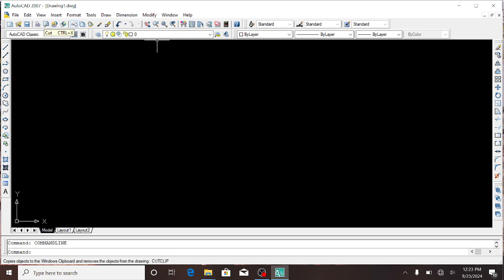In the standard toolbar, when you want to launch a new AutoCAD drawing, you can launch this from here, New. Then when you want to open your file which you have already saved, you use this. When you want to save, you click this button and it will be saved. This one is Plot. In AutoCAD, plot means just print. If you want to print your drawing or whatever you have done in AutoCAD, you can use this. And the next one is Plot Preview.